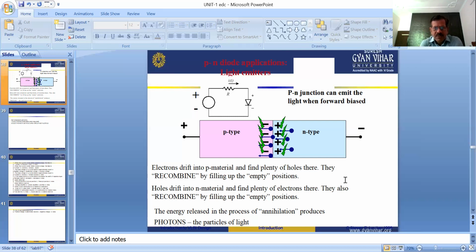The best example is a mobile charger that converts the AC signal to a DC signal of a particular voltage rating, because we know the input AC supply voltage is 220 or 240 volts, but the mobile charger needs only a 5 volt or 9 volt DC supply. So first of all, we convert the AC supply into DC supply at a particular rated voltage.